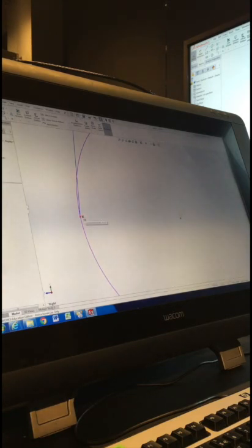This other relation here, coincident, we do want that, okay? That's the end point of the line coincident with the circle. So that's fine. At the top, we need to do the same thing. So where it's that horizontal relation with the end point of the line horizontal to the center point of the circle, delete that, all right?